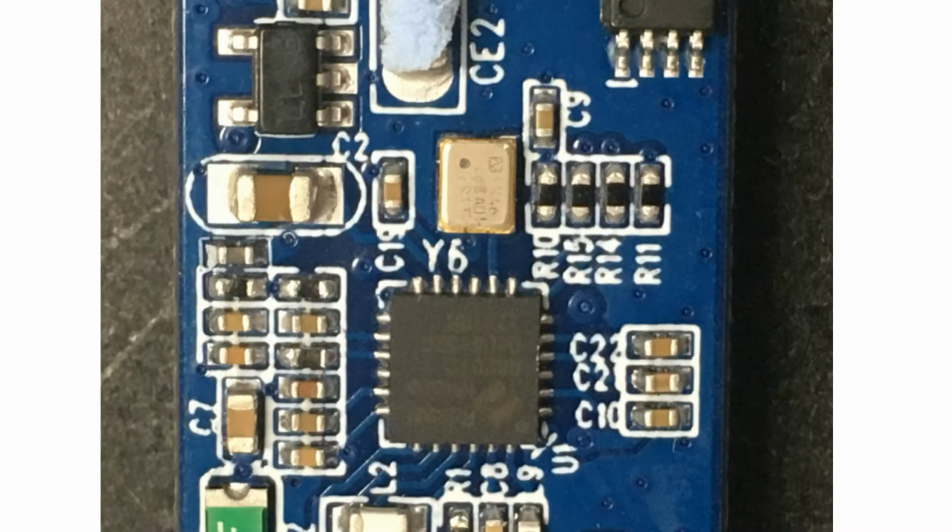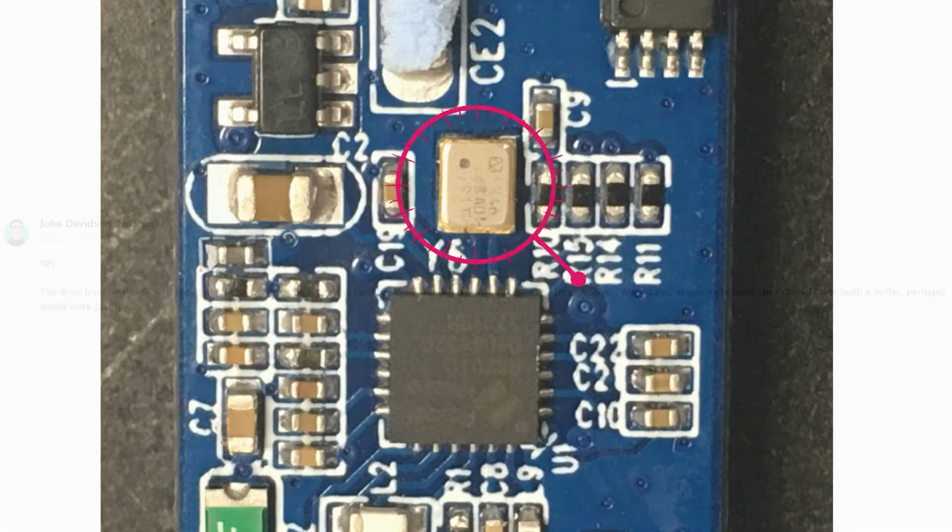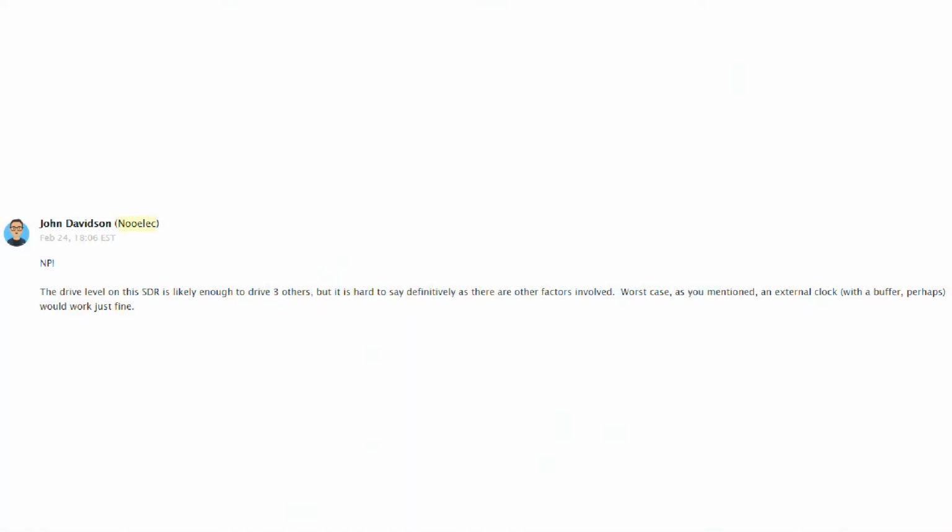The clock on the SDR regulates the operation of all ICs on the board. Think of it as the heartbeat of the circuit board. If the boards share a clock signal, then there should be no phase drifting. The SDRs may not initialize at the same exact time, but an initial constant offset can be accounted for in software, while an indeterminate drifting offset cannot.